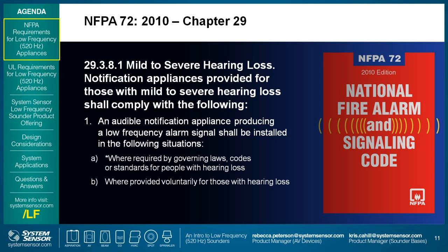They differed a little from Chapter 18, where they're required to put that low-frequency alarm signal in every sleeping space. In the 2013 edition of NFPA 72, once again, the verbiage was modified slightly just to make it clear that these devices are only intended to awaken sleeping individuals.